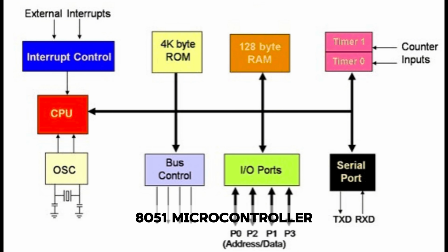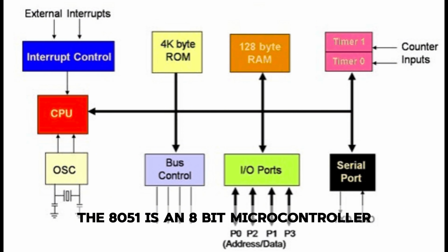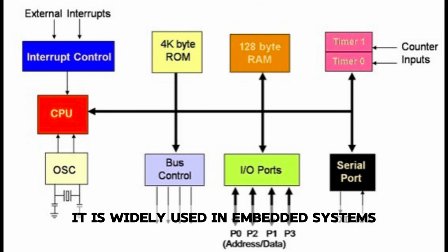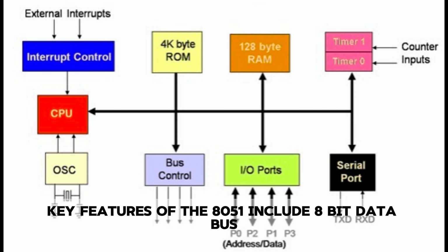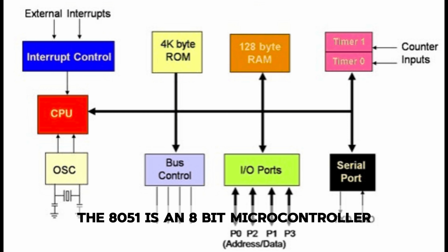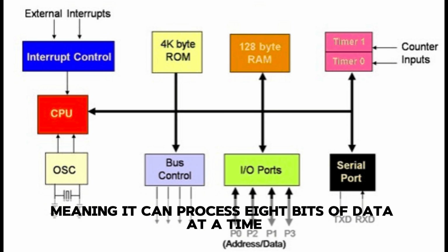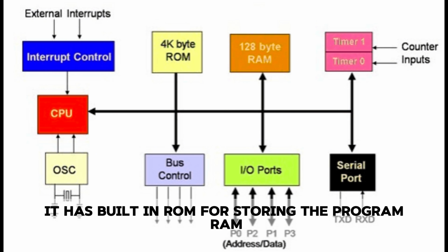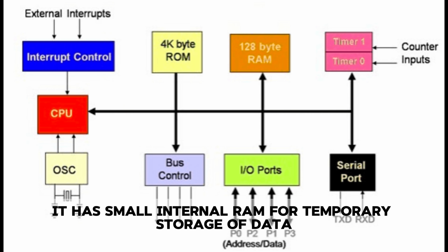8051 microcontroller. The 8051 is an 8-bit microcontroller designed by Intel in 1980. It is widely used in embedded systems due to its simplicity and versatility. Key features of the 8051 include: 8-bit data bus. The 8051 is an 8-bit microcontroller, meaning it can process 8 bits of data at a time. ROM, read-only memory. It has built-in ROM for storing the program. RAM, random access memory. It has small internal RAM for temporary storage of data.